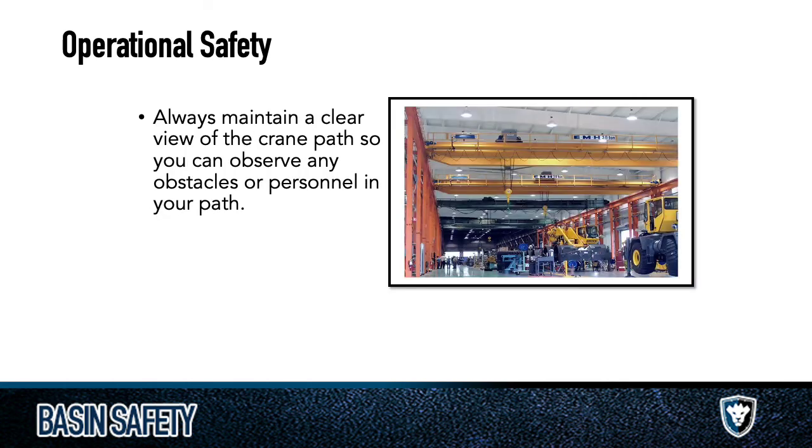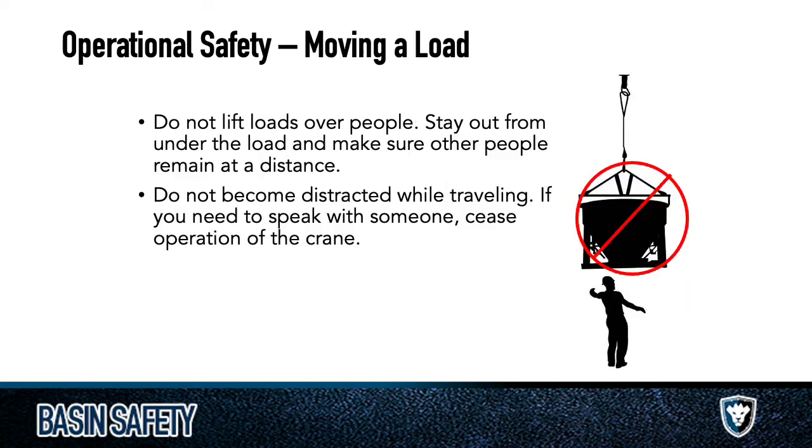Always maintain a clear view of the crane path, so that there's nothing blocking you. Move that stuff out of the way if you can. Now, there are times where you're going to be moving a load over something, for example, and that crane path isn't clear. So you want to make sure that your spotters are in a good place where they can see where everything's going and see the crane operator. You can use multiple spotters. That can get complicated, but it's better to have multiple spotters where everything is visible rather than having blind spots.